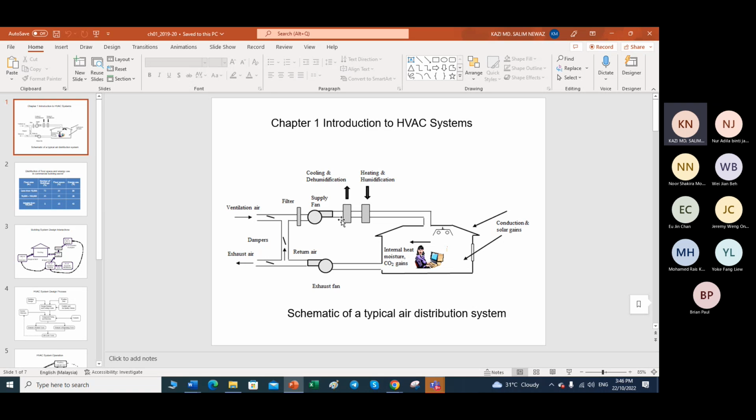And then after that, we need to control the humidification, cooling and dehumidification there, because around 60% humidity has to be maintained in the room so that you can get comfortable air conditioning. Otherwise, if it is too dry, you get a dry throat, and then you get this problem, human unease. So that is why the humidity has to be maintained, and the desired temperature, how much temperature we have to maintain there, that is to be maintained at that point.